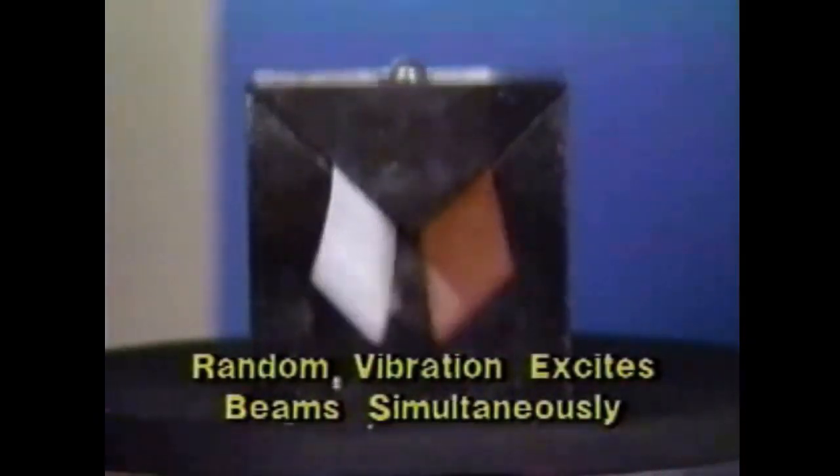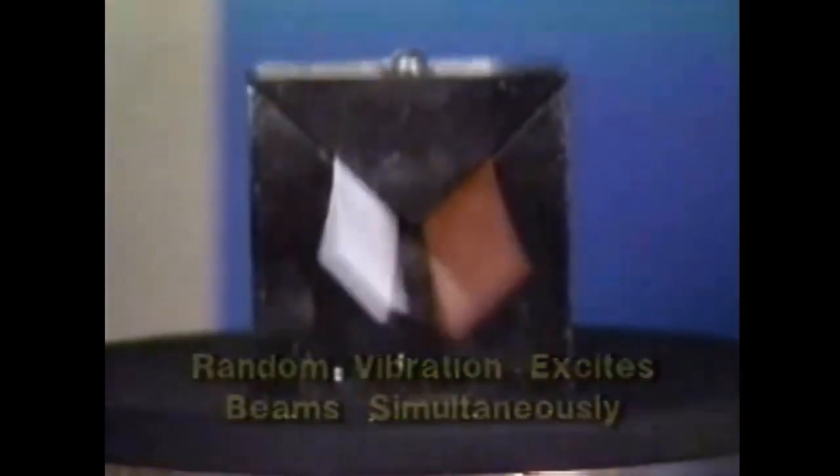How shall we define failure for this particular test? I propose that we define failure as striking together of the beams. Now we'll excite our model with random vibration. The two reeds represent two circuit boards. With a broad spectrum motion from approximately 0 to 100 Hz, we find that the reeds occasionally strike each other. Note that the response doesn't change when higher frequencies are added. The reeds are unaffected by the higher frequencies.